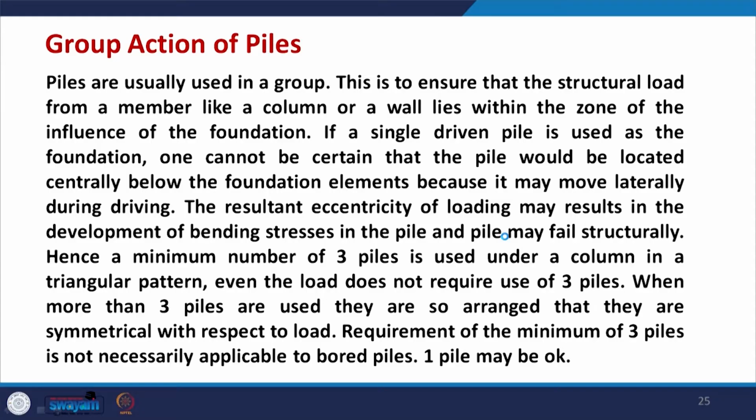So, what will happen if we do not use a pile group, and we use a single pile, and on top of this pile you have a column? This column may be transferring the load not only to the pile, but the load may get distributed, and if you are using a single pile, then it could be a problem. If a single driven pile is used at the foundation, then one cannot be certain that the pile would be located centrally below the foundation element, because it may move laterally during driving.